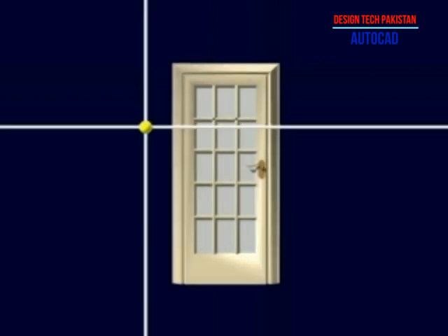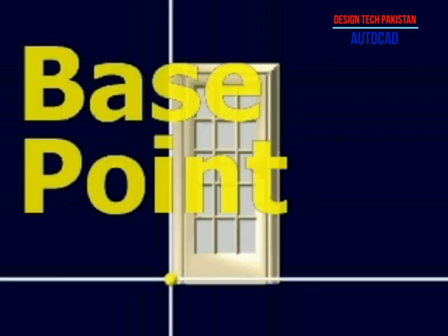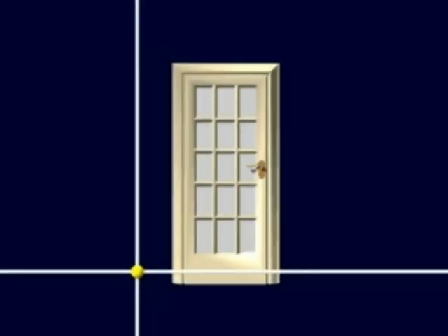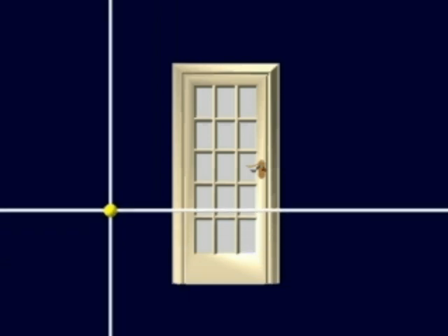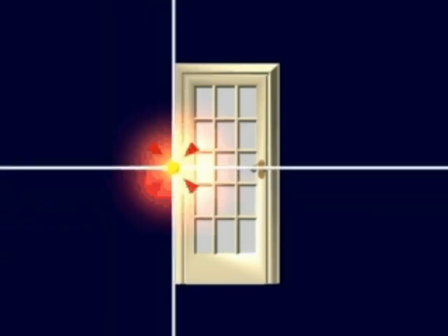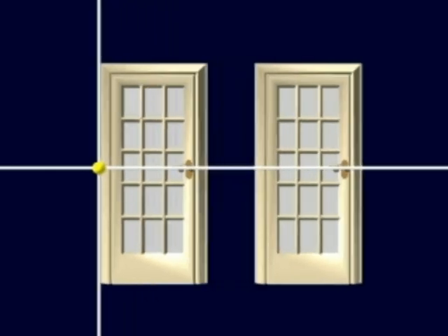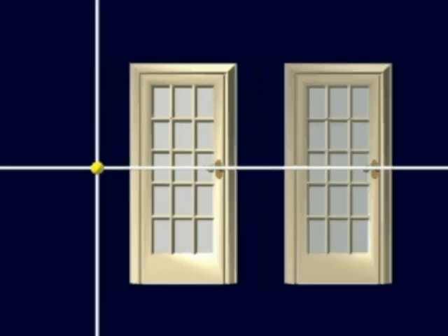In many editing operations, you are prompted for a base point. A base point is a location that functions as a convenient handle around which editing operations occur. For example, if you move an object, you're prompted to specify a base point. Your cursor is then attached to this point, and the object you are copying maintains its relative distance to your cursor regardless of where you move it.